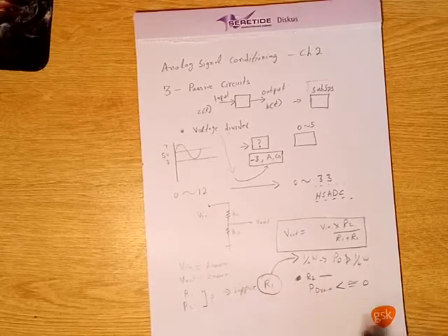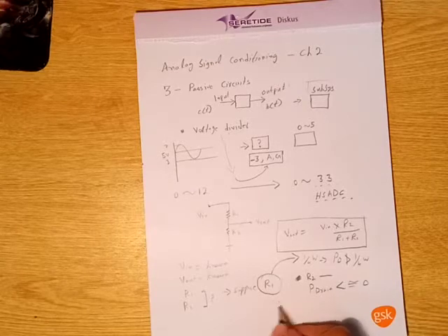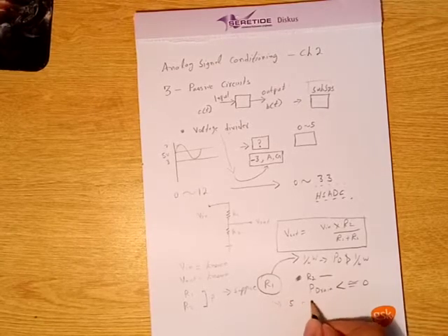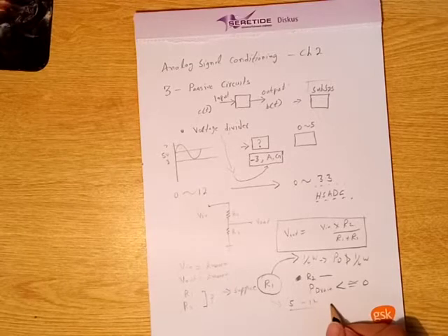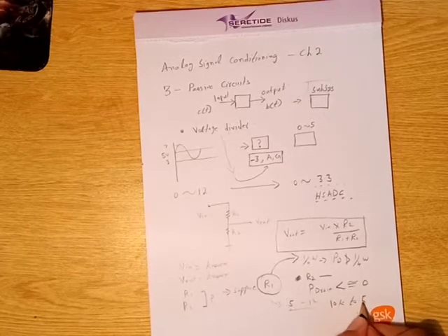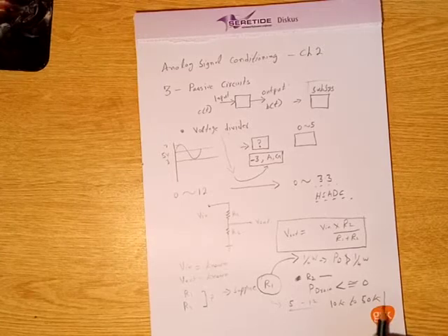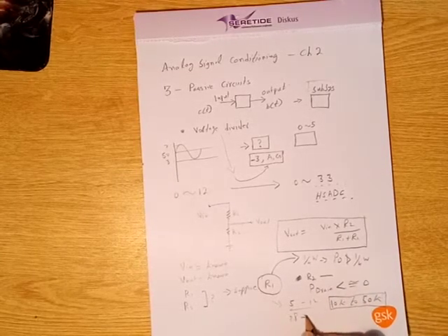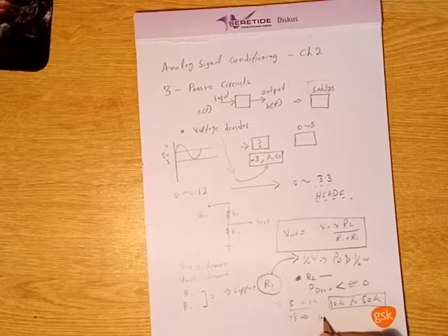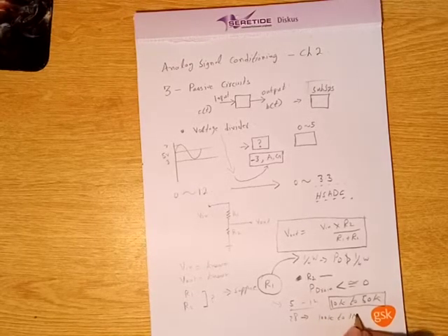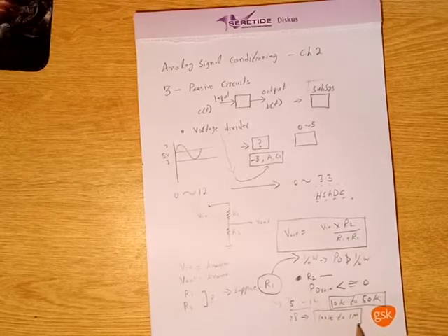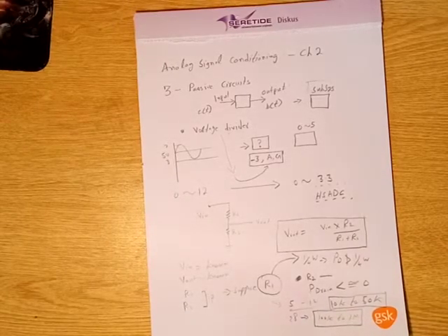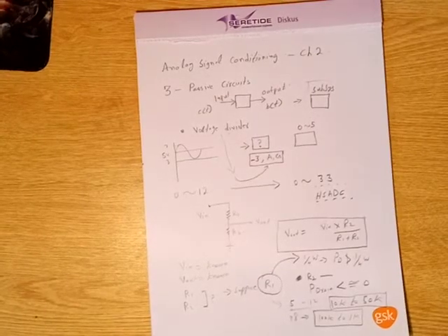So just suppose any one of them, and the thumb rule is, if you are operating between, let's say, 5 to 12 volts, you suppose somewhere around 10k to 50k to limit the power drain. If you are over that value, let's say 28 volts, you go for 100k to 1 mega. So this is how you choose it, right? So as far as voltage divider is concerned, that is pretty much the rule.